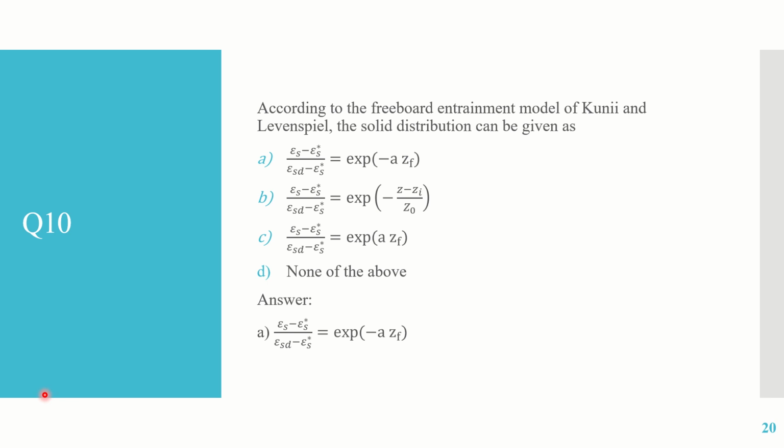And the third assumption is that the upward moving agglomerate will eventually come down, reverse its direction and move downwards. The frequency of change from phase 2 to phase 3 is proportional to the volume fraction of phase 2. That is, we have agglomerates coming with fines from the bed moving upward, and also agglomerates plus a thin layer of particles moving downward.